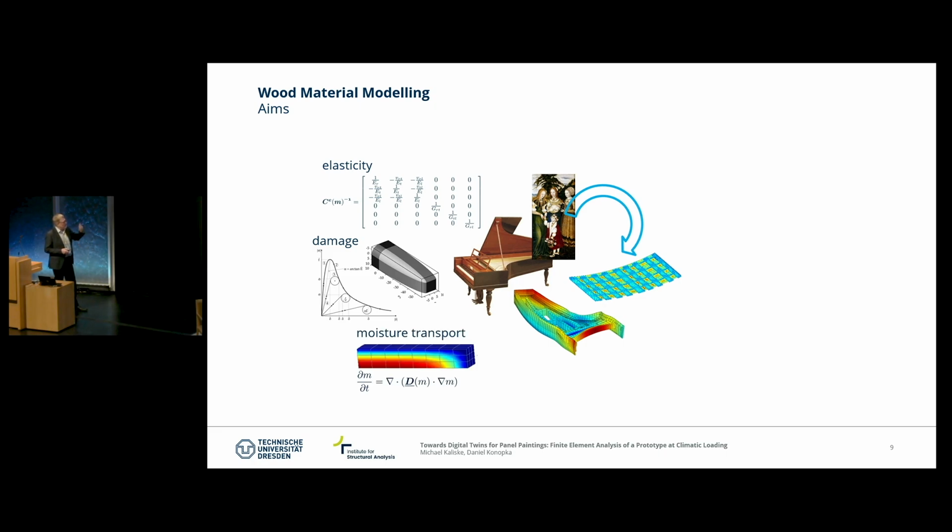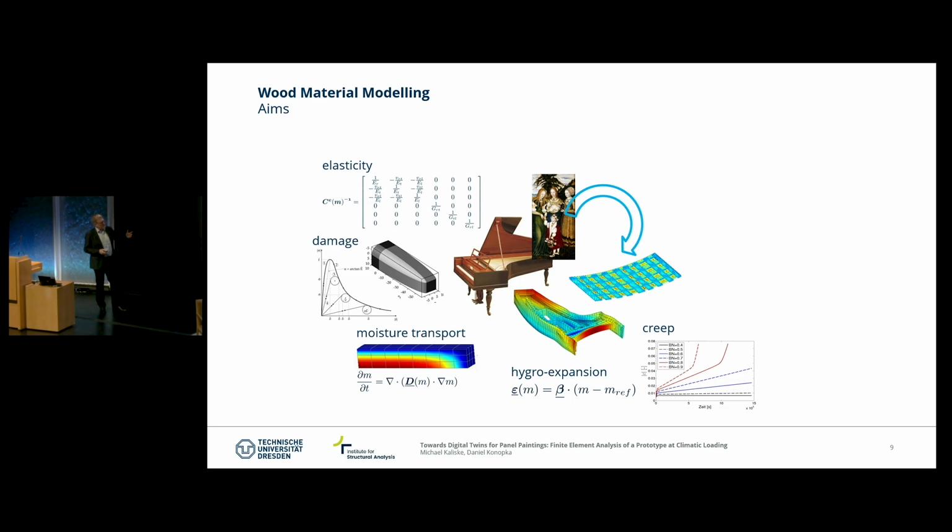We have moisture. Everything is moisture dependent. Therefore, the moisture transport has to be described. We have hygroexpansion, we have creeping, time-dependent properties. The bond lines between the fitted different components of a structure have to be taken into account. We had already presentations on that.